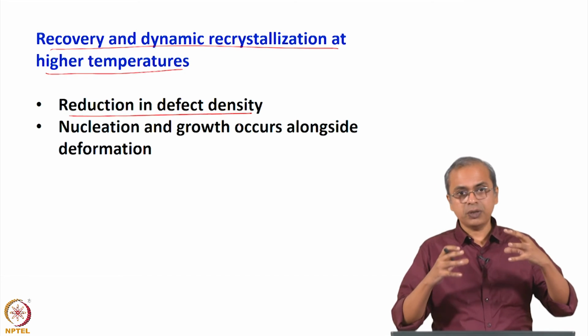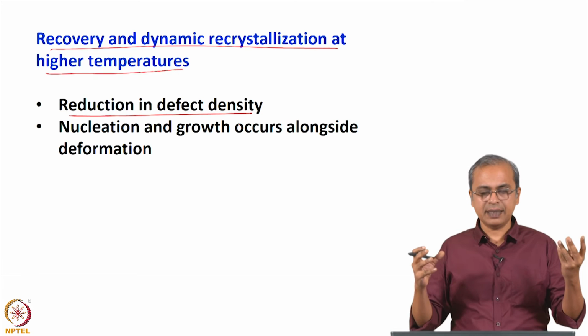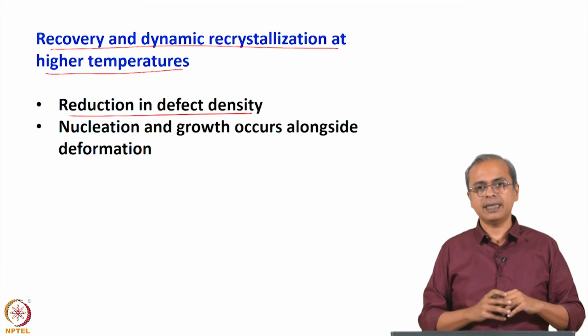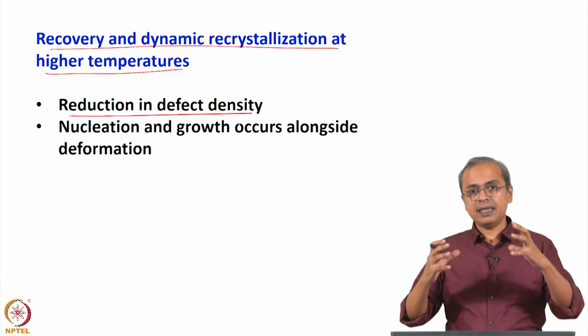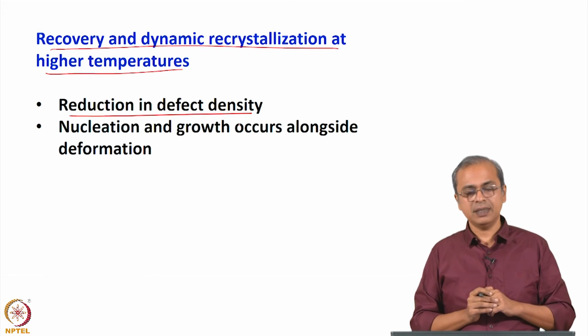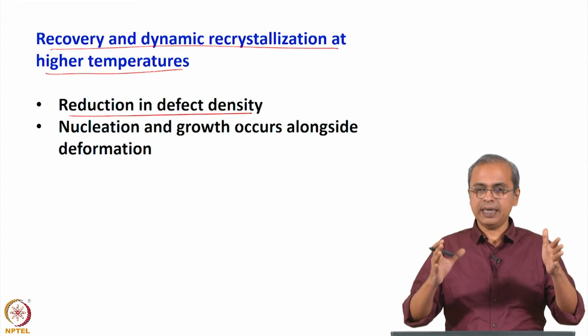Similarly, you are also deforming that crystal, so you are changing its shape, you are changing its aspect ratio, etc., usually also associated with increased energy. So if you give it the right kind of conditions, which usually means a high enough temperature, the system would like to go back to a lower energy state.